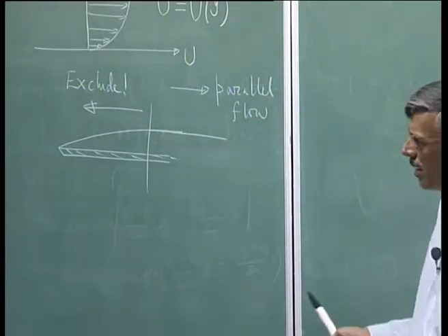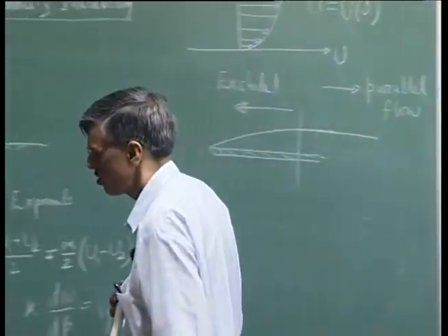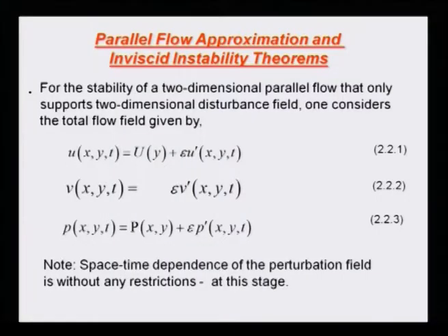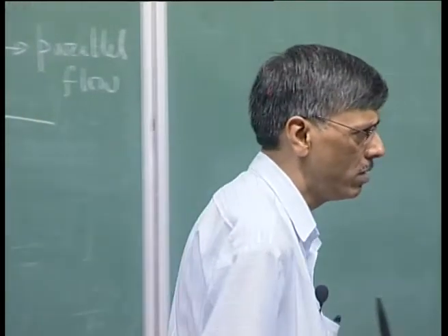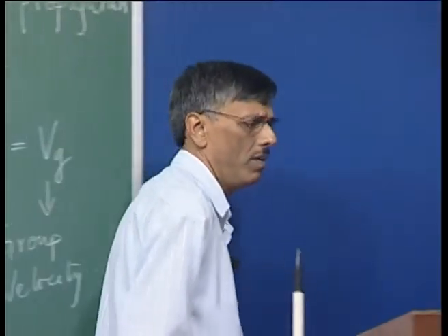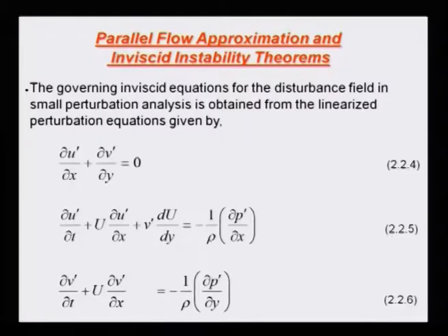Right? Then of course, we also start with the paradigm of inviscid studies. Let us see what happens. Okay? So, this is the way that we are going to talk about it, and I specifically made a note here that the space-time dependence of the perturbation field has not been restricted, while the mean flow has been restricted here. Okay, so we try to write down the governing equations.